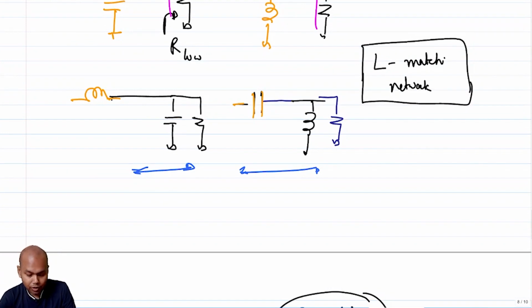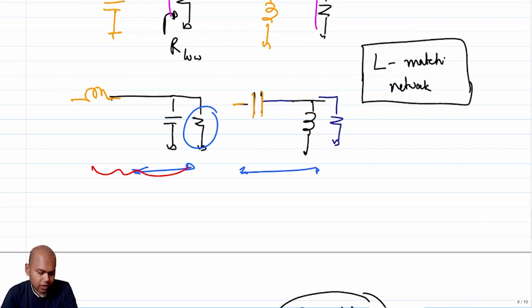Now, if I do not give you any other information, then you can choose any. But if I tell you that along with this resistance there is a parasitic capacitance associated with the network, because maybe a transistor gate is connected to it or something like that, right? Then probably this will naturally be a better choice, because this part of this capacitance already exists, right?